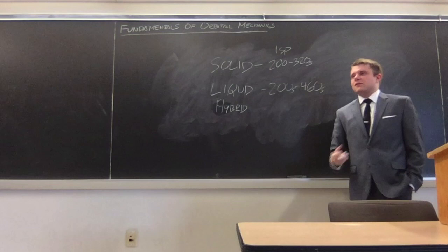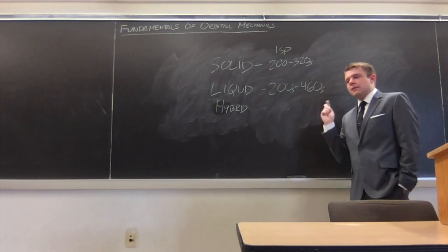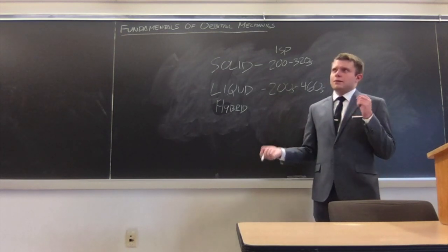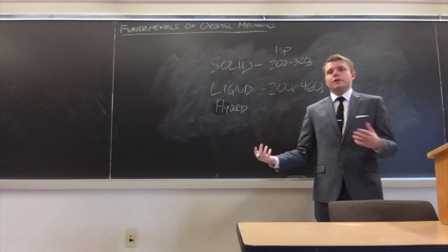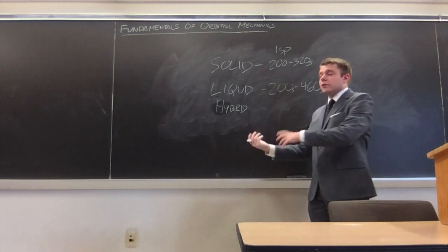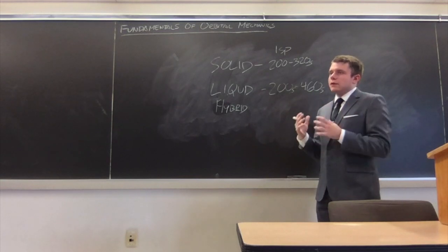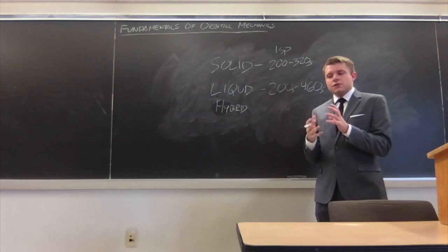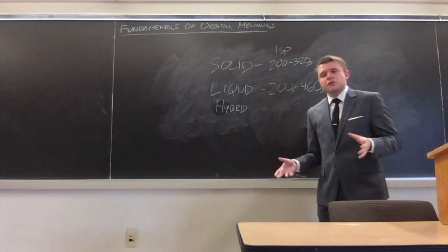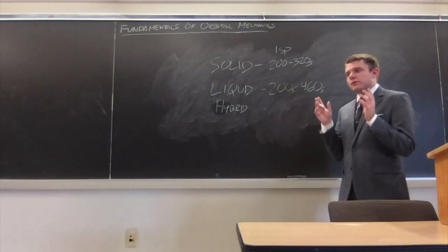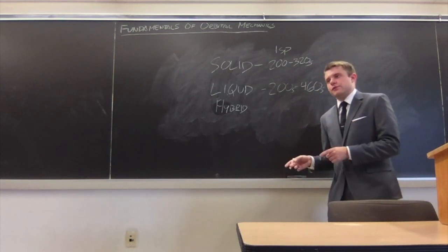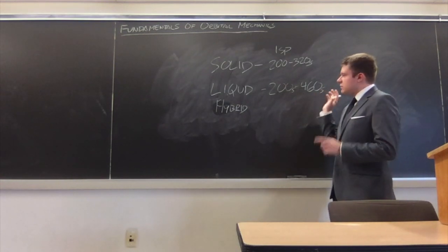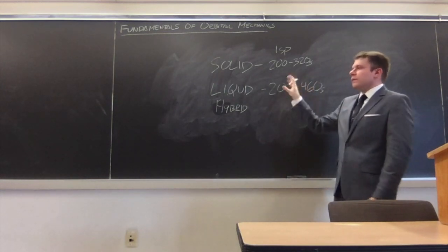It's because their exhaust products are water and hydrogen gas, because they're not burned stoichiometrically. If you remember from chemistry, if you do it stoichiometrically, you get, I believe, just water and nothing else, because you're combining it in just the right ratio with no leftover products. But when you burn stoichiometrically, you get the highest possible temperature for that given chemical combination, and you wind up in a position where your motor basically liquefies itself, and that's not a good situation. So most rockets operate either fuel-rich or oxidizer-rich. I will cover this more in a separate lecture series in the near future, but just keep that principle in mind for where we fall in the performance level.